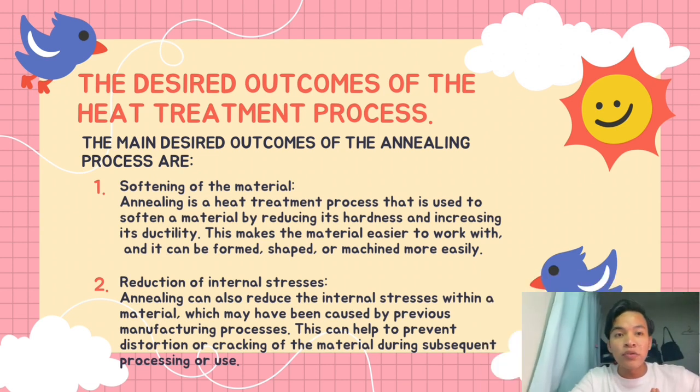For this point, reduction of internal stress, annealing can also reduce the internal stress within a material, which may have been caused by previous manufacturing processes. This can help to prevent distortion or cracking of the material during subsequent processing or use.